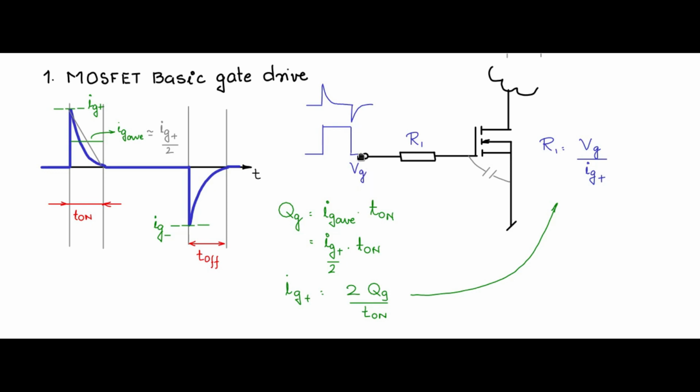Here you are making it 0, and the Vg should have sinking capability. There should be current capable of flowing in the negative direction. So whatever charge is there in the internal capacitance will discharge through R1 and the external Vg circuit. Therefore you get this negative pulse and charge removal. This way the MOSFET will be turned on and off.